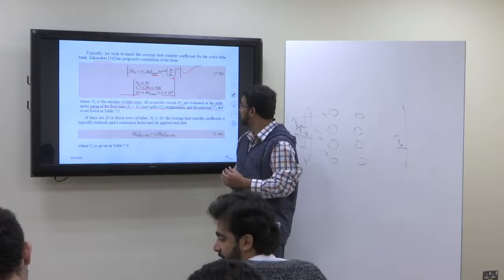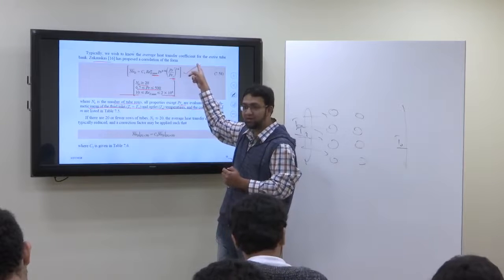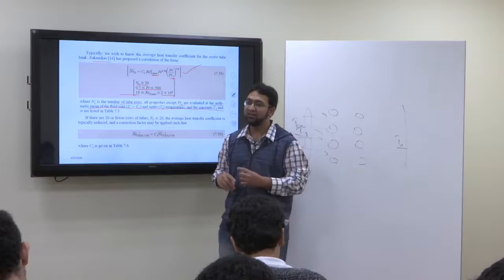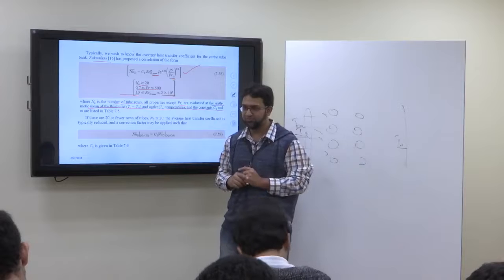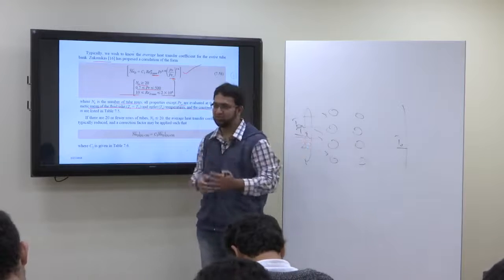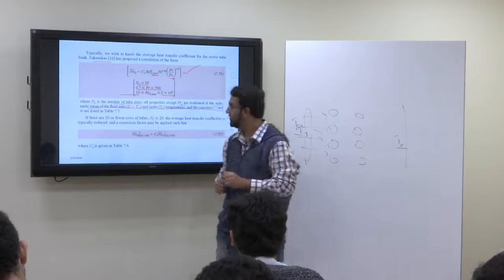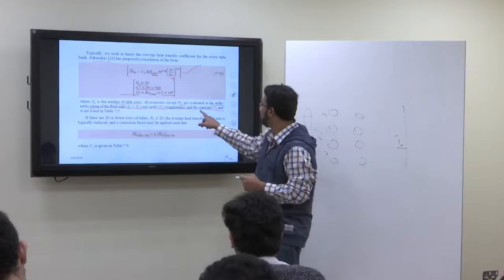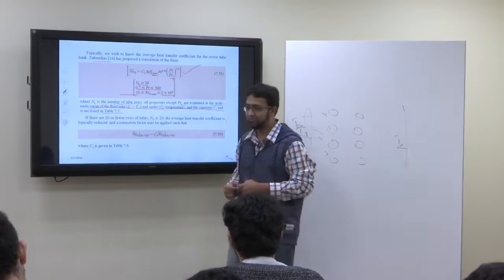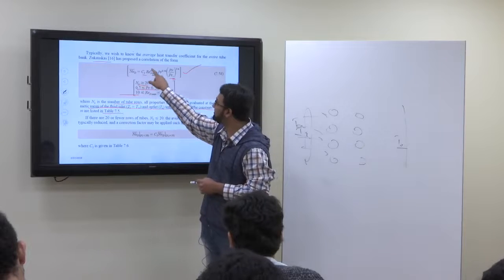So the properties here are not calculated at Ti, they are not calculated at To, they are calculated at an average of Ti and To, because in this case the free stream's temperature itself is changing as it passes through the bank. Is it clear? The constants C1 and m are listed in table 7.5, which gives you their values.